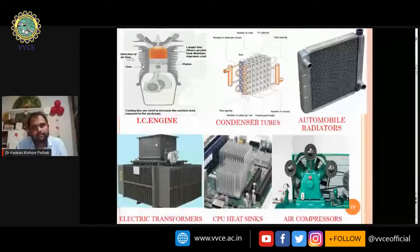Similarly, flat plates are rarely used in the case of condenser tubes. Similarly, radiators also, and electric transformers. And you can see this is the motherboard of a CPU, where you can see how heat sinks are used. These heat sinks are nothing but extended surfaces. Similarly, in the case of air compressors also, protruding parts are there. These are fins. In almost all engineering applications where we need to remove heat rapidly, we have to use fins as extended surfaces.